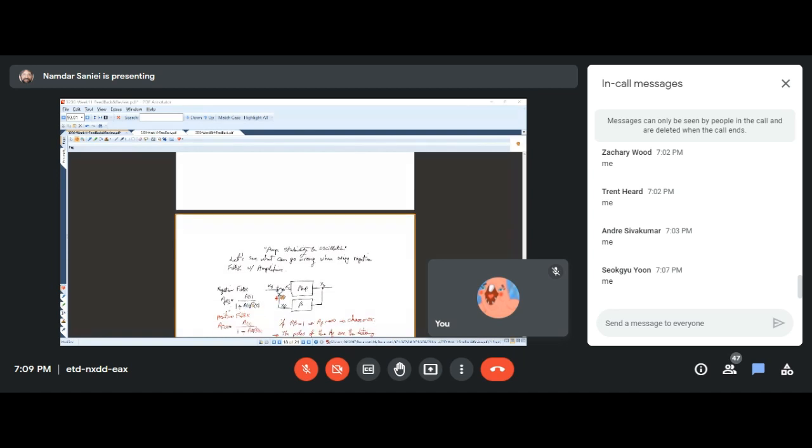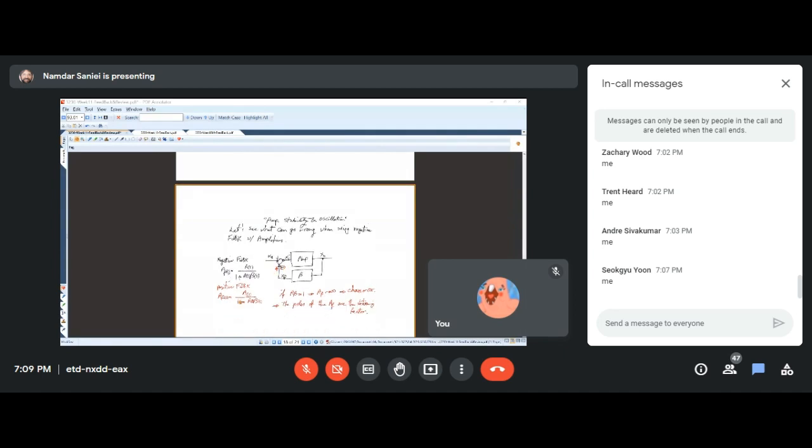However, if this negative that we had would turn out positive, what we would get in the denominator would be 1 minus A beta. Now, if A beta would become 1, this could go to infinity. And going to infinity is not something definite, right?